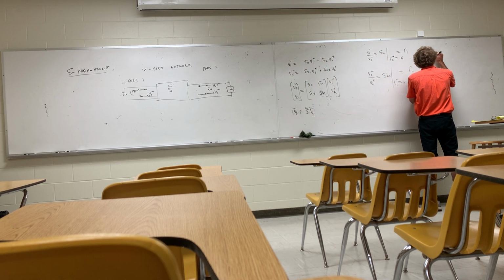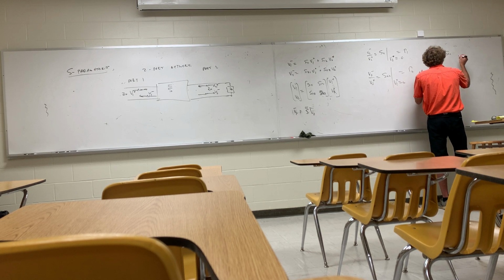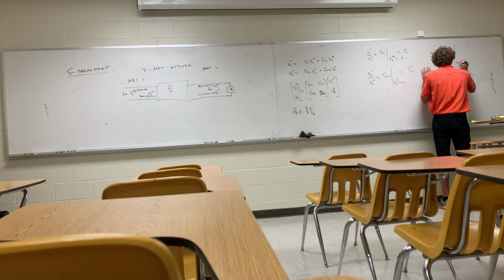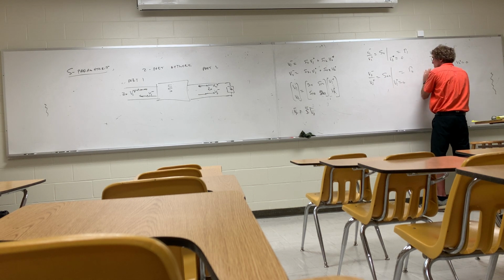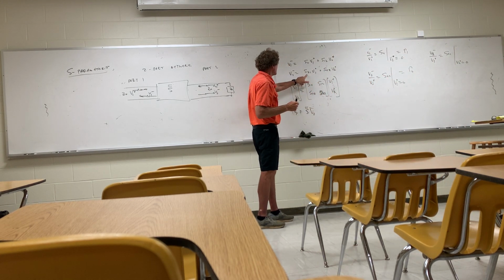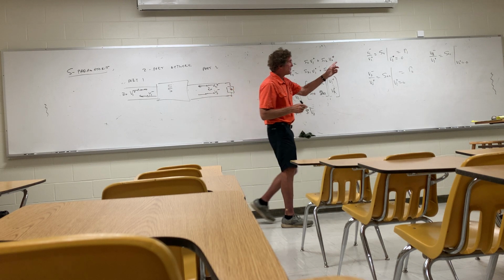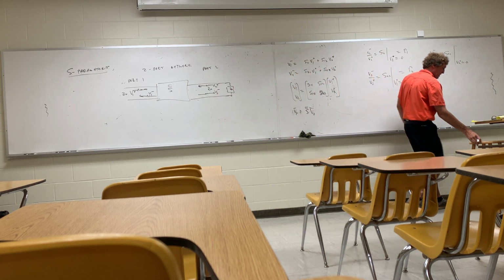if I take V2 minus over V1 plus, that is S21, and it's assuming that V2 plus is 0. And here's what I mean by that. If I look at S21, it would be V2 minus over V1 plus, assuming V2 plus is 0. You all follow me? That's called the forward voltage gain.